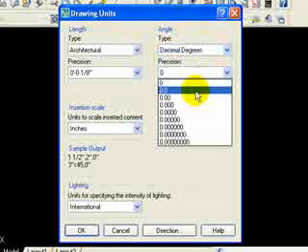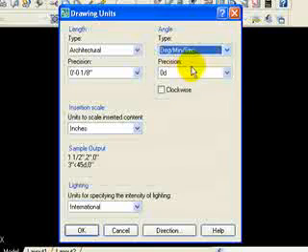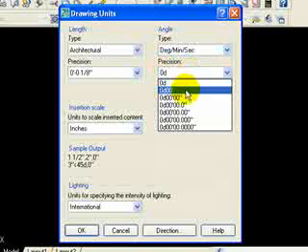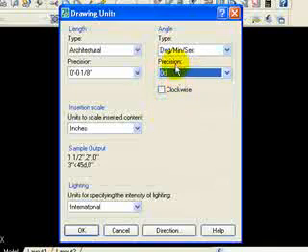This is obviously 0.0 in decimal degrees for the angle. I'm just going to do degrees, minutes, seconds just so that you can see. Precision is to the degree, degree and minutes, degree and seconds, and then degrees, minutes, seconds plus 1 decimal, degrees, minutes, seconds, 2 decimals, and so on and so forth. So you can set up your precision for your angles as well.